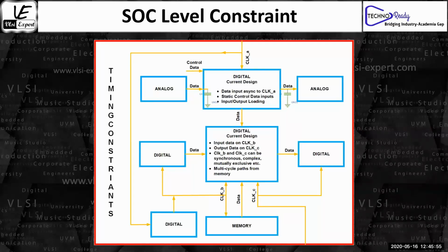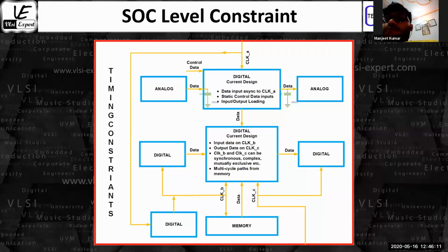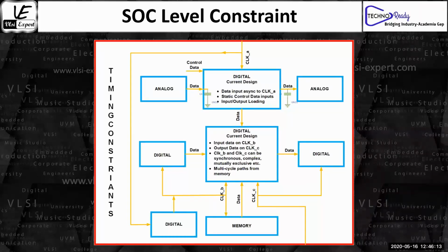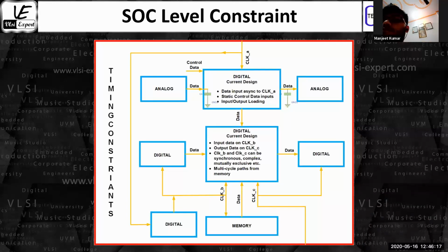Second, their noise might be different, which adds different uncertainties to them. So you are supposed to write clock domain crossings for synchronous clocks using FIFOs. And then you can also do clock domain crossings for asynchronous clocks. When we say asynchronous, it means that two domains have no timing relationship between them at all.